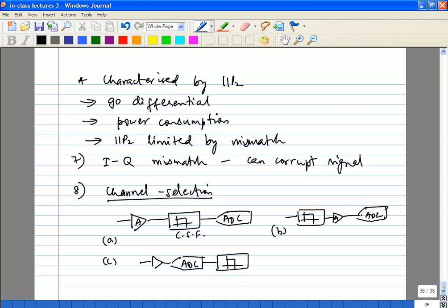Is the amplifier a normal amplifier or an AGC amplifier? It can be an AGC amplifier. It most probably will be. As in a VGA, not an AGC. It will be a variable gain amplifier. The AGC comes in from the overall system. It won't come in from the analog path.